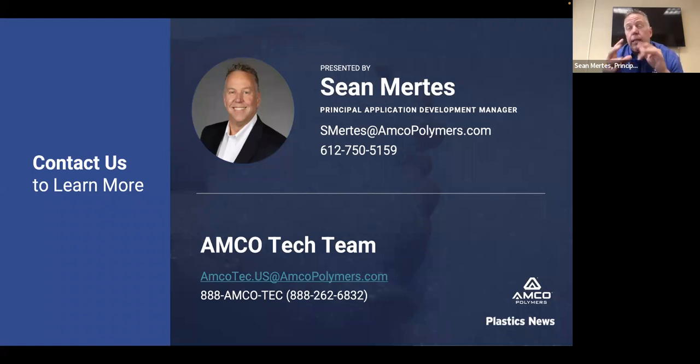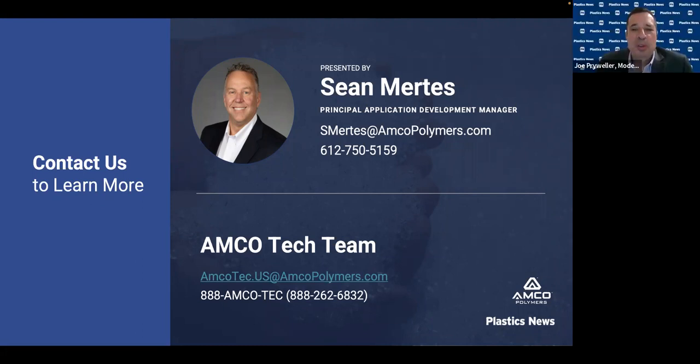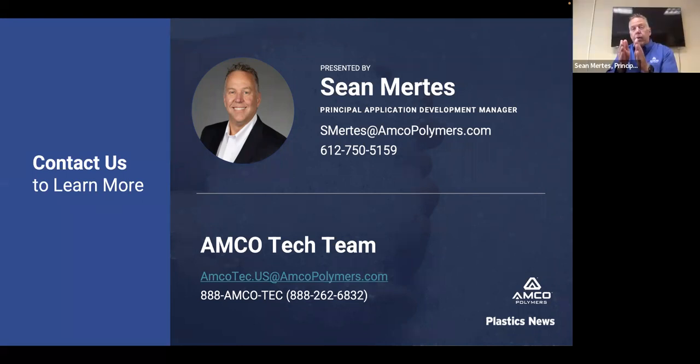So that's typically what happens if I'm running glass filled nylon with a foaming agent, and my internal core temperature stays hot. Once again, if I take my temperature, hold your camera on that temperature. If my temperature comes out at 360 degrees, right, 360, and my temperature may come out at 360 at my skin, but then all of a sudden it goes 360, 362, 365, 370, 380, 390. If it starts rising, that tells me my internal core heat hasn't come out yet.